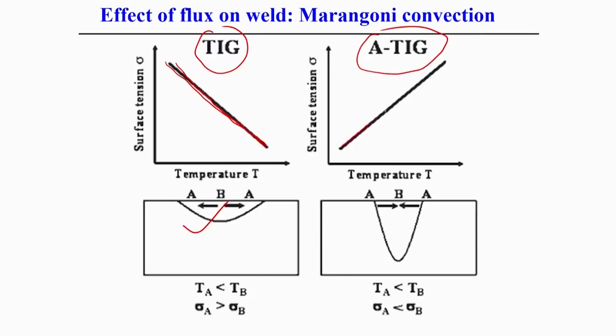So, in that case it simply changes the slope of the surface tension gradient, and that actually brings this kind of profile, that means low width and high depth of penetration.